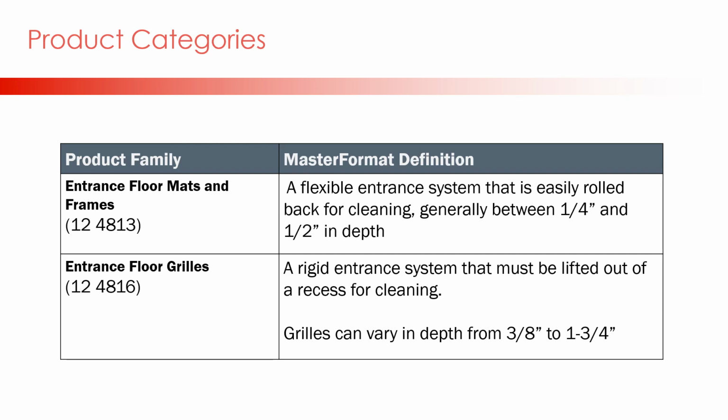1. Entrance floor mats and frames are listed in Master Spec section 124813. Mats are defined as a flexible system that is easily rolled back for cleaning. They are generally between 1/4 and 1/2 inch in depth.